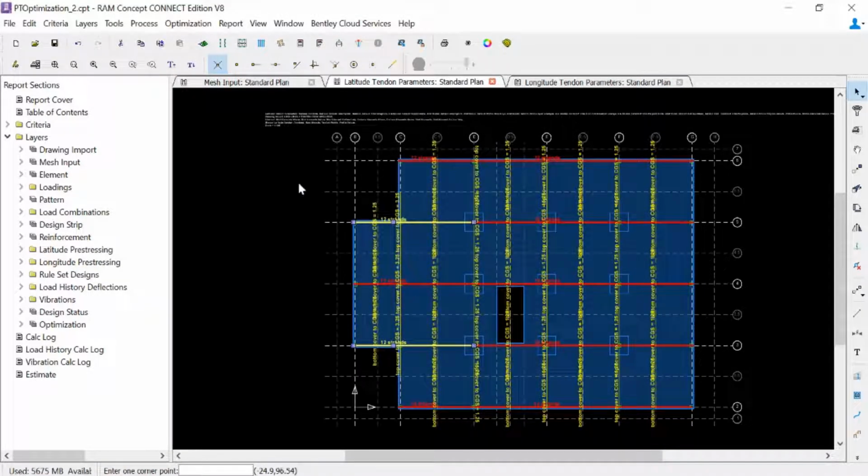If I wanted to, I could take this a step further and assign groups to my profile polylines to ensure that the elevations are symmetrical about this center grid line for my particular model, since that's my choice to force that. Now let's talk a little bit about what's going to happen along grid line F here. If you remember, I set up optimization regions for my model.